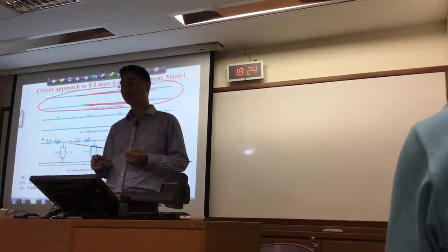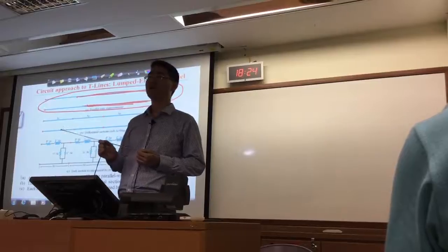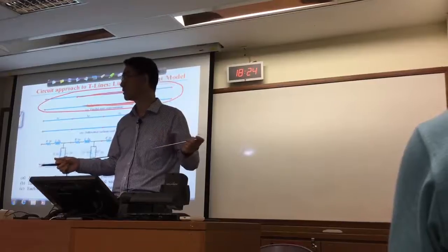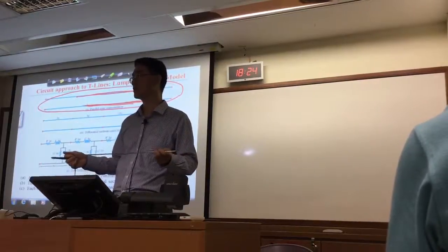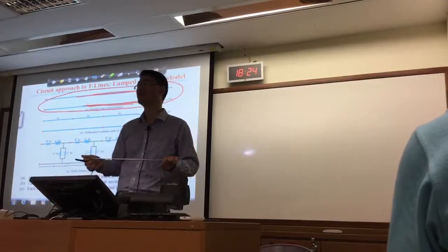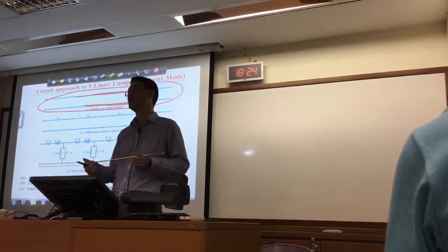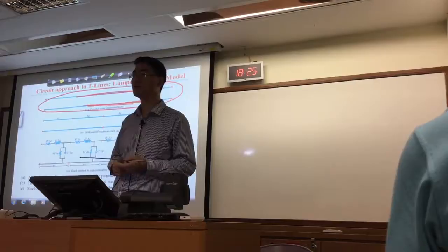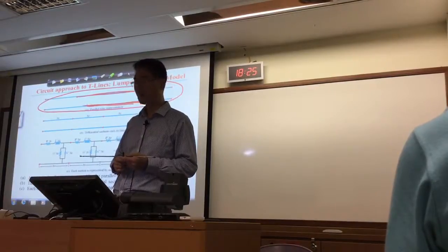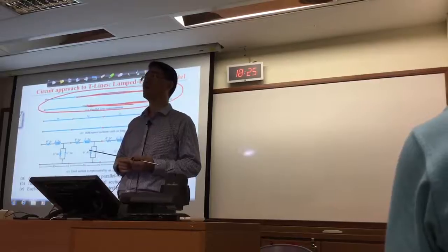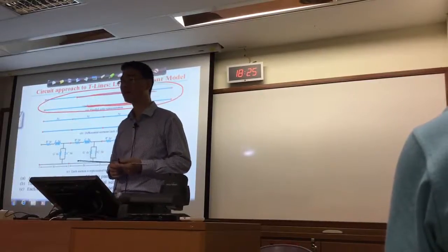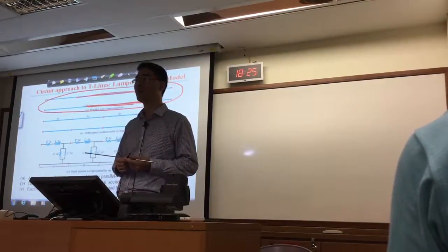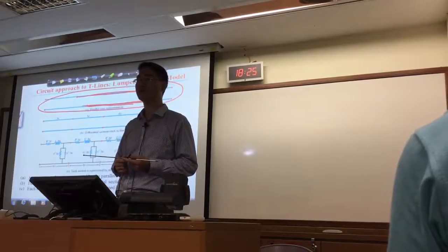Okay, so now we have no idea whether this transmission line's physical length is much smaller than the wavelength. Typically it is going to be comparable, so you cannot directly apply the KVL and the KCL. Then I would pose a question: can we still use KVL and KCL for an RF microwave transmission line? The answer is yes, we still can, but we need to do some further step before we apply the KVL and the KCL to the transmission line.